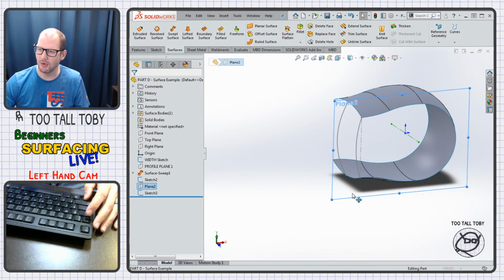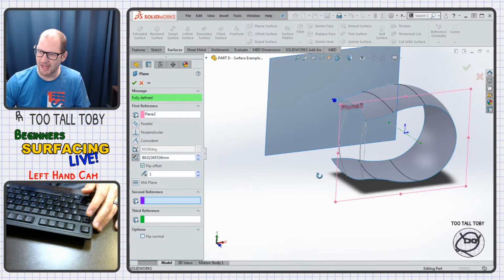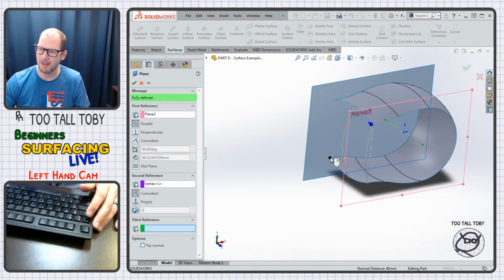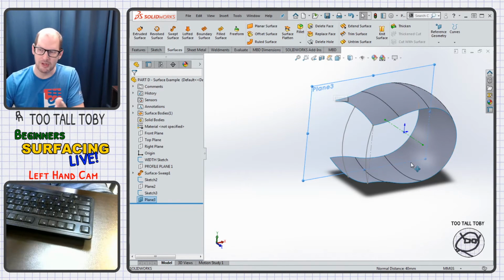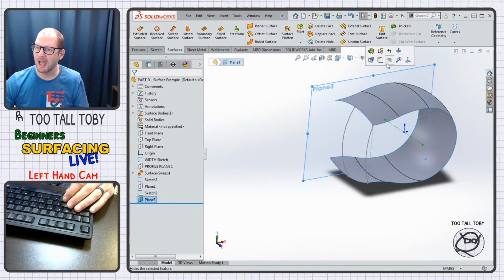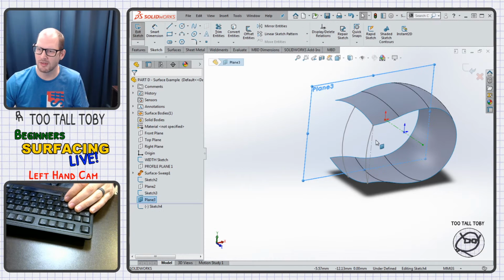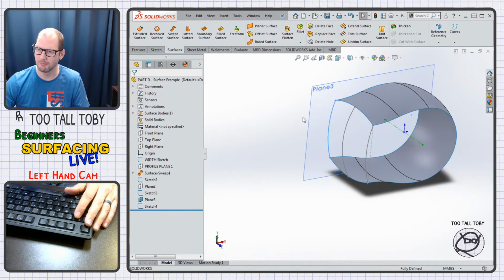I'm going to pick this plane, hold control, left mouse button and drag. I'm going to pick this point here to make a new plane parallel to the first one at that point. And then normally I would probably properly create another sketch and pierce it. But for sake of time, I'm just going to say that I want to convert the geometry from this sketch onto that new one. I know this thing is symmetric, so I actually probably would just model half of it and mirror it depending on how complicated it gets downstream.